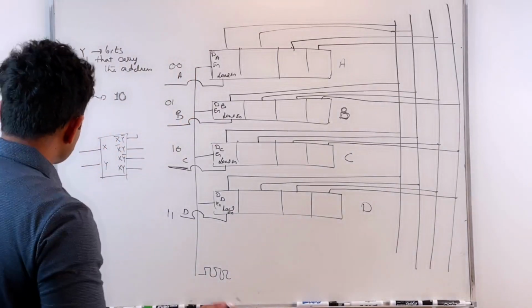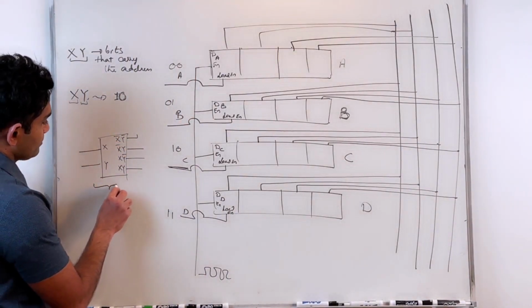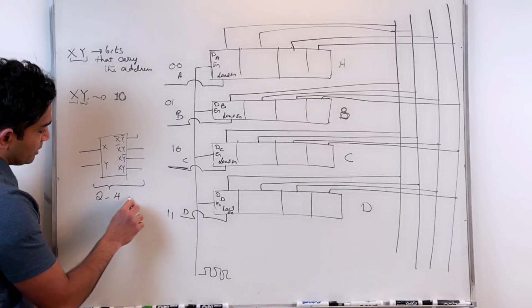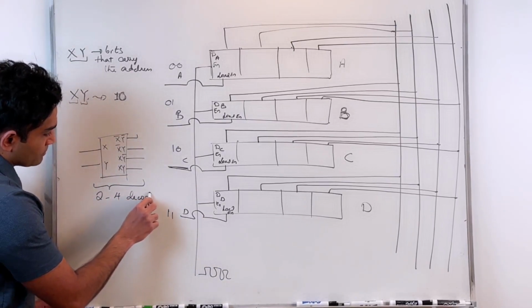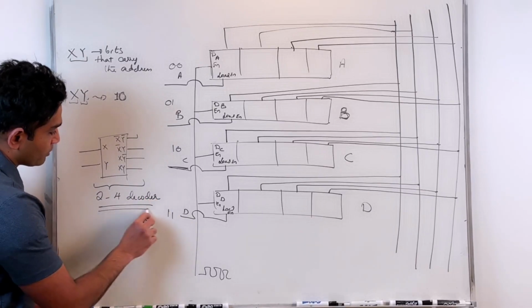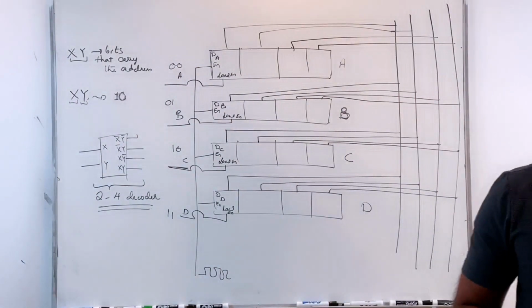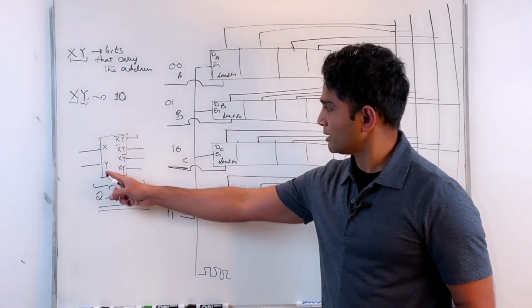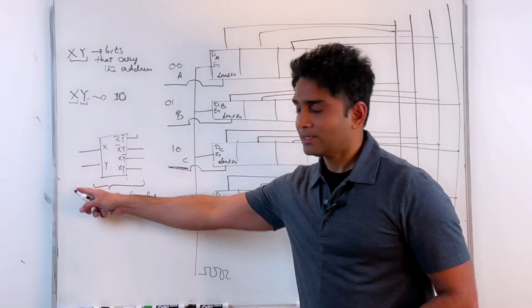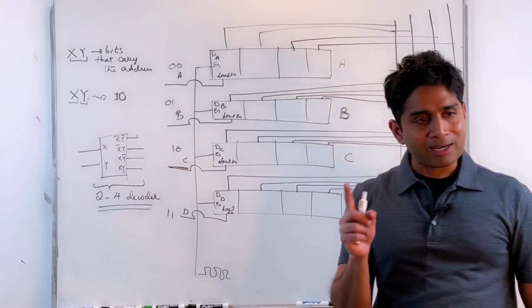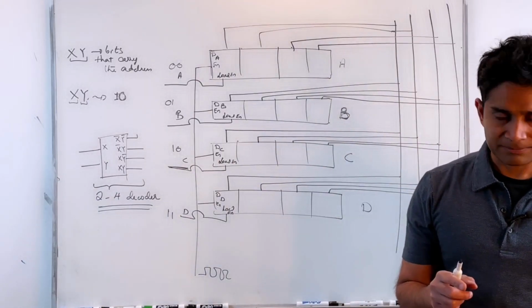Okay, and this particular circuit has a special name. It is called a 2 to 4 decoder. A decoder can be very helpful for these applications. So basically, I have a 2 line to 4 line decoder, right? I'm taking a code, and based on this code, I'm only making 1 line active at a given point, right?